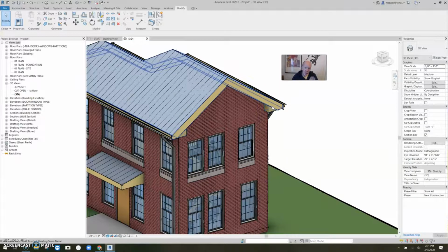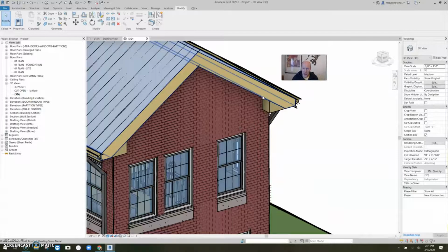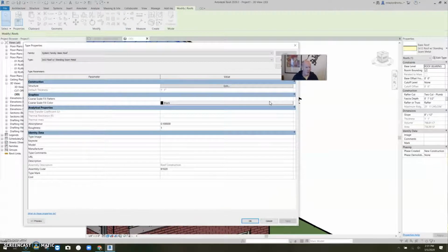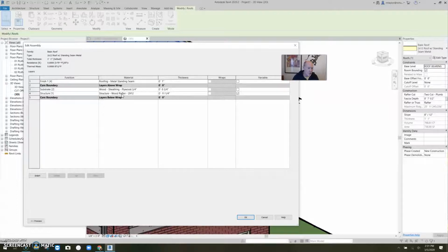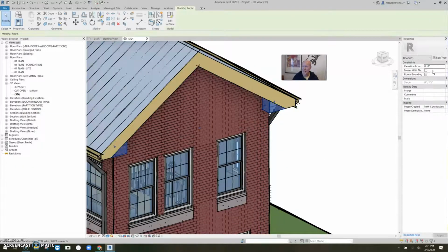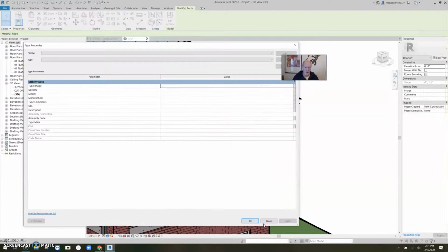And if these are the exact same material, I can use join geometry. And let me just see if join will make that and the roof clean up to each other. Okay, let me get the materials correct here. Let me find out what this material is. I'm going to show you how this works. We got time. Okay, structure. Okay, that is a wood rafter 2x12, okay? And so if this is the exact same material, okay, wait.